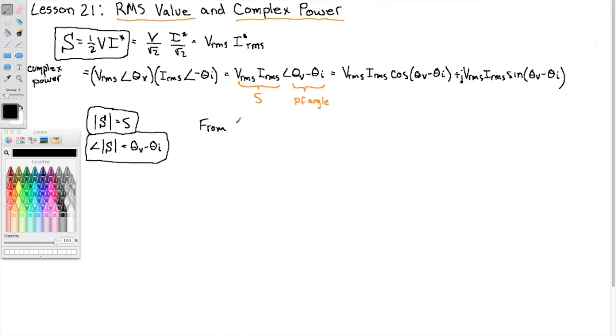Now, from Ohm's law, of course, the voltage current relationship across and through an impedance is related to Z by Z equals V over I. And this is a phasor, so Vm angle V over Im angle I. So again, V has a magnitude and a phase, I has a magnitude and a phase, and if I divide the numerator by the square root of 2 and the denominator by the square root of 2, I haven't changed the fraction. Right?